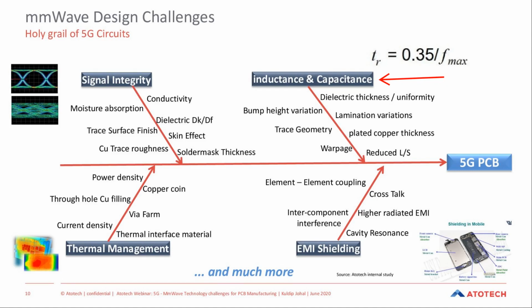This means that the physical and electrical connections in the circuit components do not affect the circuit operation. Another challenge that we're going to talk about, which is really hot, as you could say, is thermal management. As PCB and components are heated, we know that the properties change when they get heated. We also know that thermal conductivity and electrical properties affect each other, and these effects can lead to performance issues. And as 5G continues, we see the demand for higher power, increased functionality and increased I/O density is definitely going to mean that we have to have higher power. That means there's going to be higher thermal issues in the future.